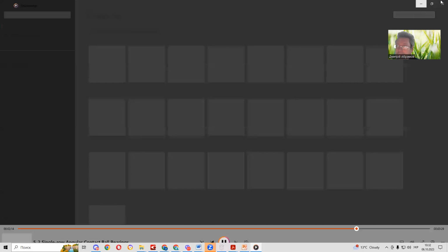For interference fit, the tolerance field of the shaft will be equal K5, K6, M5, M6, N5, N6, P6, R6, R7. IT grades can be 5, or 6, or 7.